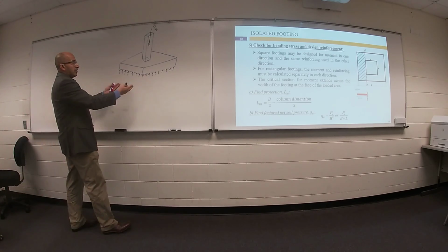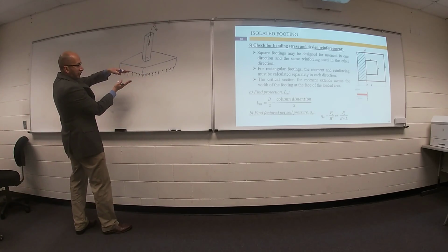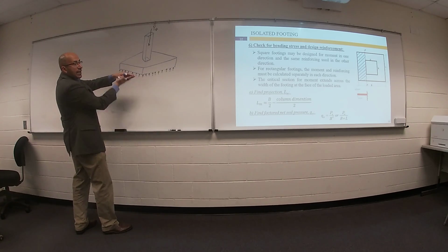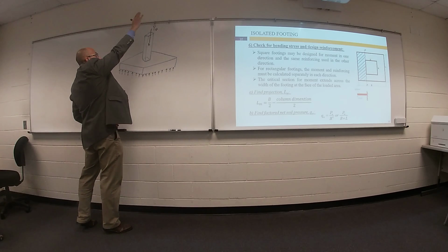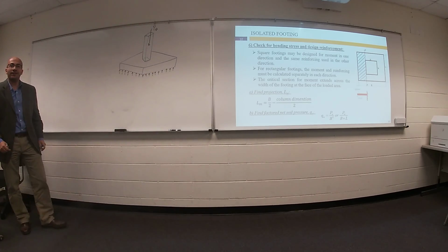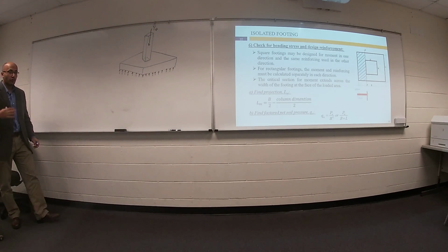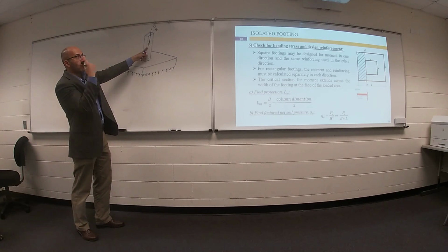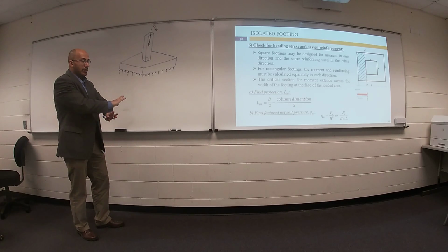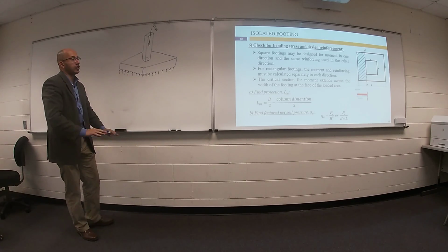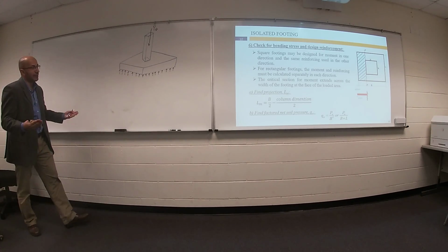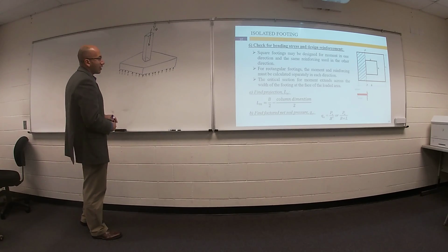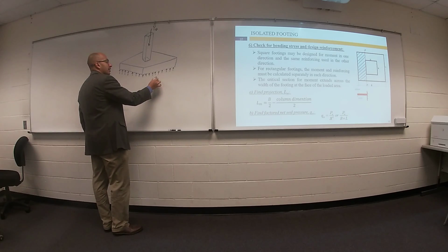So the surface of footing, the contact surface between footing and soil, we have pressure trying to support the applied force. Do you agree? So I converted one concentrated load at one point to surface load on the soil. So I can expect the soil will react by pressure called Q ultimate.